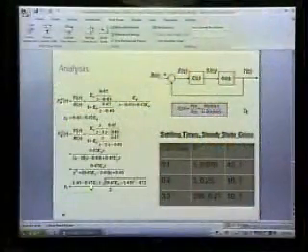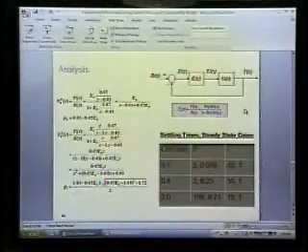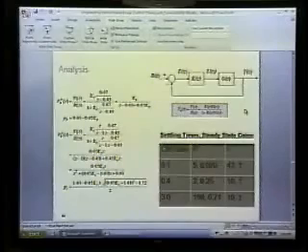Now we know from the first order approximation that settling time is going to be -4 divided by the natural log of the largest pole. So from that we can invert back and figure out what that largest pole can be, because I've got settling time as my goal. I can take the inverse function of that and figure out what the pole is going to be. Once I've got the pole, I've got this equation right here, and I can solve for Ki for that pole. So that's the way you would go about this with a single variable.